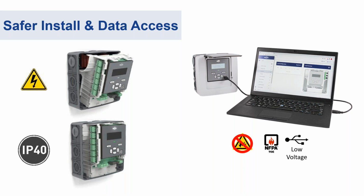What are the current capacity ranges that can be monitored with these devices? Or maybe in a different way, what is the CT maximum? What is the CT maximum current capacity? Yeah, great question. So with standard split core CTs from Setra, you can go up to 400 amps load. And beyond that, if there is another compatible standard CT that meets the signaling characteristics that is compatible with our meter, which should be widely available on the market, then you can use larger than 400 amp loads.